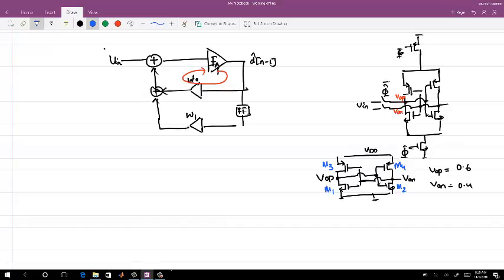So if you want, you can always get the small signal incremental picture of how it regenerates. But this is just an intuitive thing. Which one gets stronger first, and it gets a little strong, and then you add more voltage, it gets more strong. Okay. So in a comparator, because you are resolving a very small input, you sample the input in this circuit, and then you allow it to regenerate to become a 1 and 0.